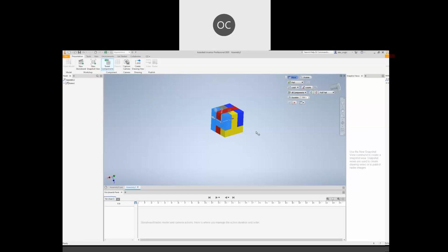Once you click on the part that you want, you will have all the directions available to you, which will be the Z-axis, the Y-axis, and the X-axis. For example, this part itself, I want to move back to forward here, on my left-hand side. The second step is on the arrow itself: left-hand click and hold to drag to a specific distance.